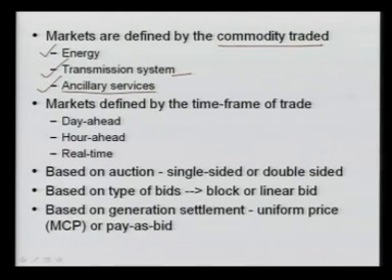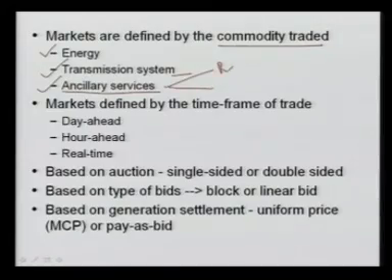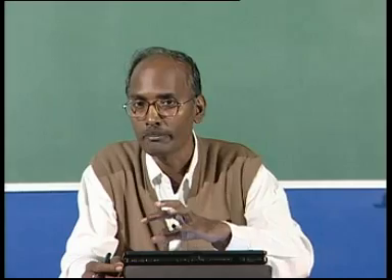The ancillary service market is another important one, because in a conventional or regulated power market, ancillary services were with the utilities. Ancillary services are nothing but the reserves, whether static reserves, installed capacity or spinning reserves. We also have to go for voltage control and frequency control. All of these, even the imbalancing of power, are ancillary services. So we have another market, and these three markets are running parallelly.